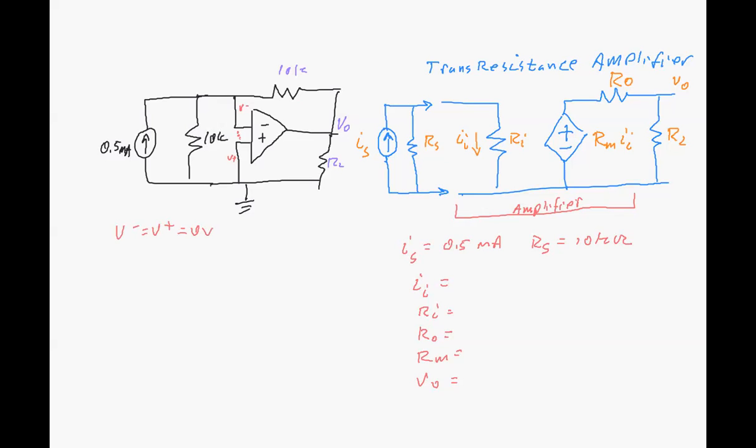That means if we've got 0 volts over here, and we've got 0 volts over here, then we have 0 amps flowing through that signal generator's source, that source resistance RS. We have no current flowing in there because we've got ground on both sides of that. Is this useless? Is this dumb? Is that stupid?